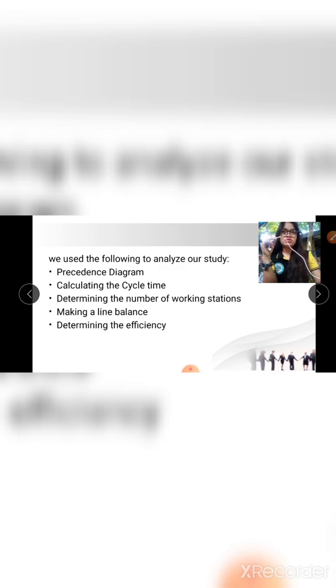As the assumptions in making a case, the method of assembling the camera module comprises the following steps: placing the substrate on a positioning die with 90-second process time; irradiating the lens assembly with parallel rays of light with 40-second process time; placing a lens assembly comprising the convex lens in an axial direction with 60 seconds process time; measuring the light intensity of light passing through a spot hole by means of a light sensor accommodated in the positioning die with 30 seconds process time; determining an optimal position of the lens assembly on the basis of an obtained light intensity curve with 70 seconds process time.